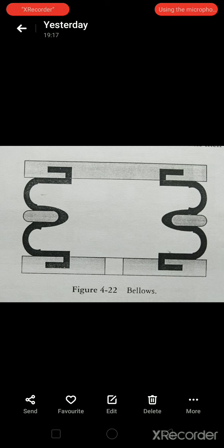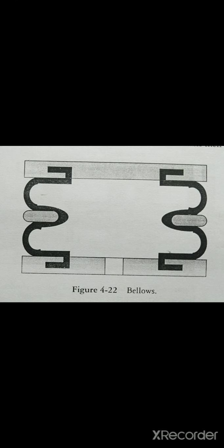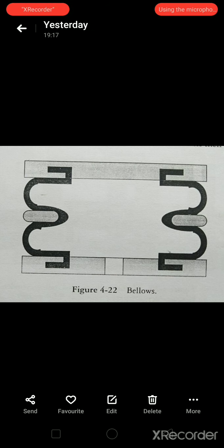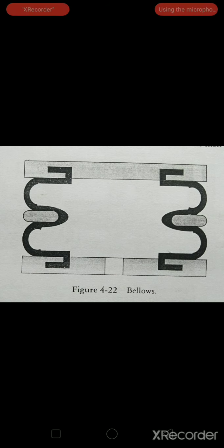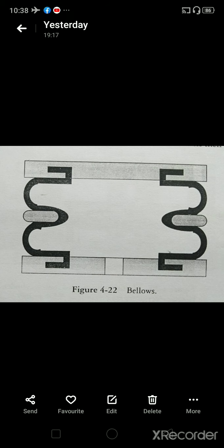The bellows actuator must not be pressurized while unrestrained, as it will overextend, and the end plate is likely to be blown free, which could cause serious injuries. In the de-energized state, the bellows actuator is deflated and the loads will fall under gravity. It should be noted that maximum extension and compression of the bellows must be limited by external restraint. When the bellows actuator is exhausted, it must be prevented from crushing by the load. So this is what is required to be taken care of.